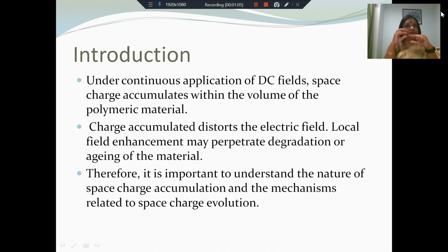So electrons which flow into the material may give up a very small quantity of energy and come to occupy the shallow traps. I have mentioned before that when the energy difference between the vacant energy level and the conduction band is very small, we have what are called shallow traps. When these energy levels are much further away, closer to the valence band, then they are called deep traps. So in a material, we generally have vacant shallow traps and deep traps because of the lattice structure, impurities, and material deformities. They are very often present as free energy levels.